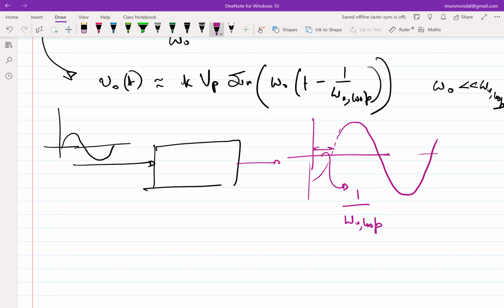Okay, so we'll not get too deep into what happens if you have delay. This is not a delay in the loop per se, this is the end-to-end delay. But what I would like to point out is that omega u loop plays a very important role, especially at low frequencies, because you can model this entire thing as a delay element also, right? It's a block which not only amplifies your signal, but also delays it. Now sometimes that delay might be wanted, sometimes it might not be wanted. It depends upon what you are trying to do. As the case he was pointing out, sometimes you want a linear phase filter. In case of a linear phase filter, maybe you would want a delay, because a linear phase translates to constant delay, right?